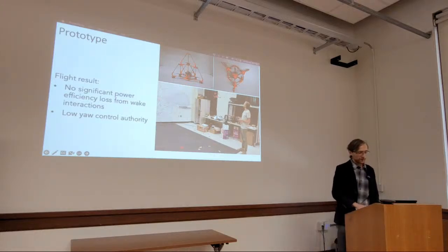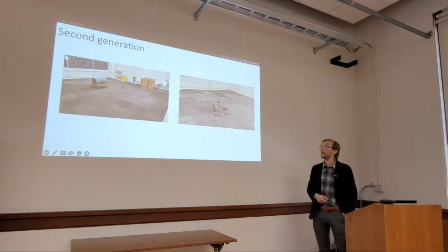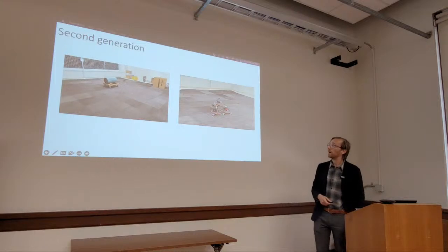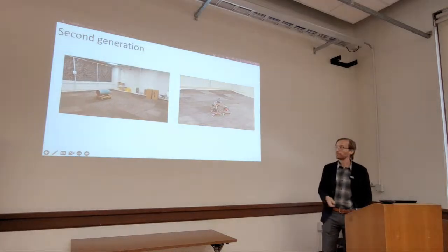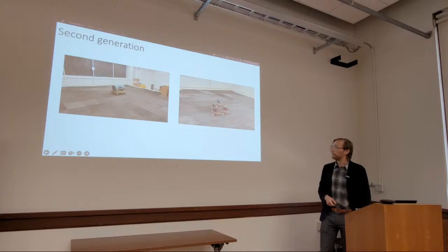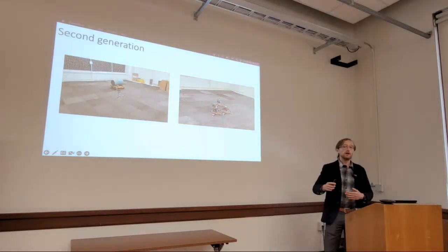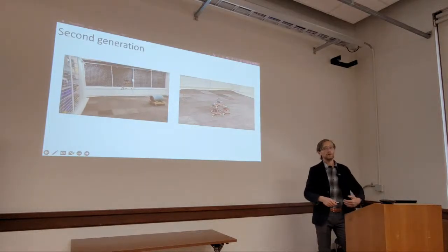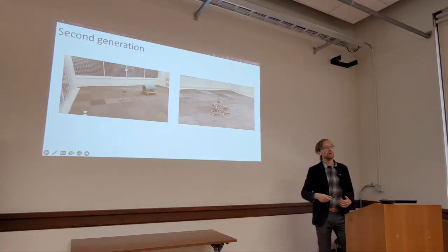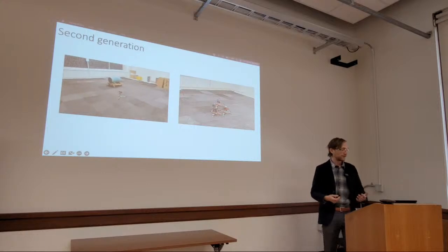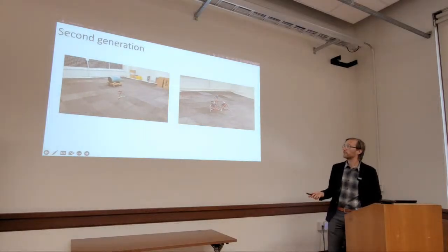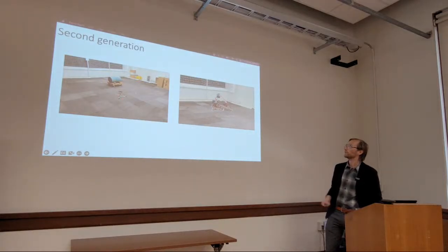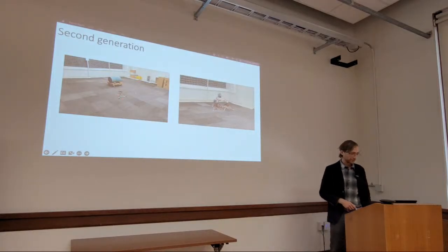But we still flew it, and another iteration of the prototype was built that was lighter and more efficient, and that didn't have this issue, because there was more leeway in the input of the rotors available before actuation saturation is reached. So here you have a first iteration with 4 rotors, and the second iteration here with 16 rotors.